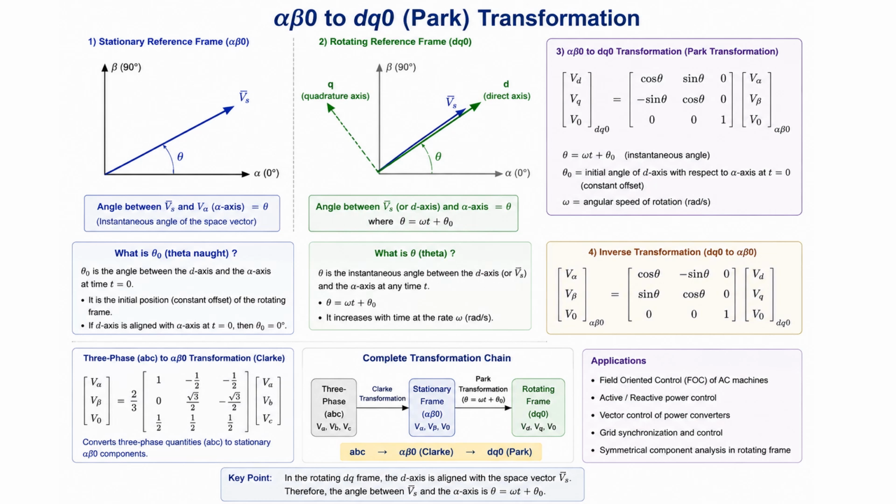So here the fan, assume it as the space phasor Vs. Now ourselves, we can assume as the DQ frame. So we have to align with the fan wings like that. Vs is rotating at one speed. The DQ frame is also required to align with Vs in such a way that if you control the D or Q components, you can control the A, B, C components.